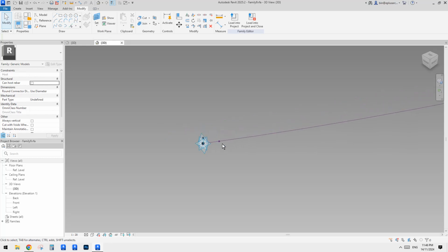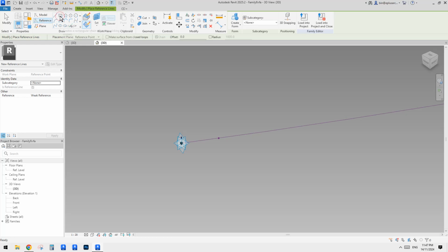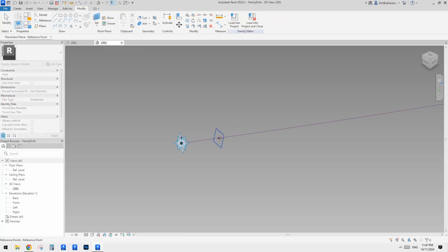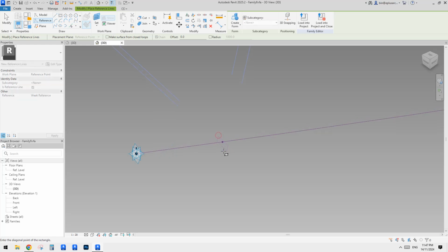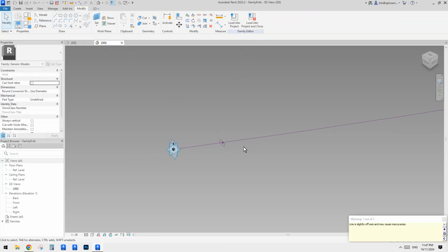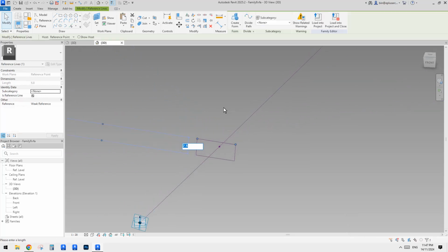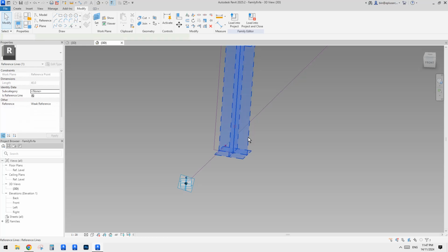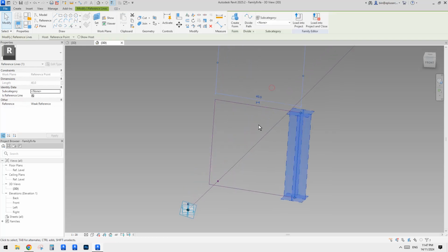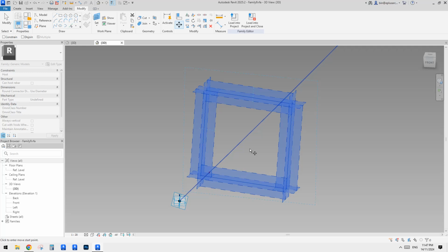Then we'll place a profile onto this. Now I'm going to change this one from a circle into a square. Let's use reference rectangle, draw on work plane, set work plane, pick this, and then I'll just draw something. Don't worry too much about that. That's too small, so I'll make it maybe 40 by 40, and then I'll move it, maybe to the midpoint here.